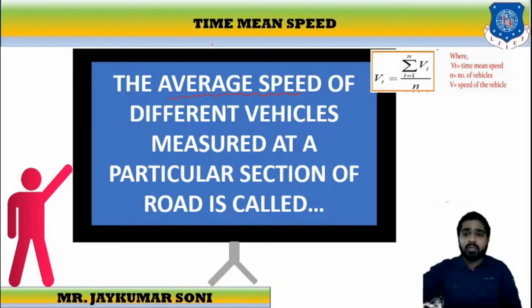This is the equation of time mean speed: Vt equals the sum from i equals 1 to n of Vi, divided by n, where Vt stands for time mean speed, n stands for number of vehicles, and capital V stands for speed of the vehicles. So we have discussed time mean speed.